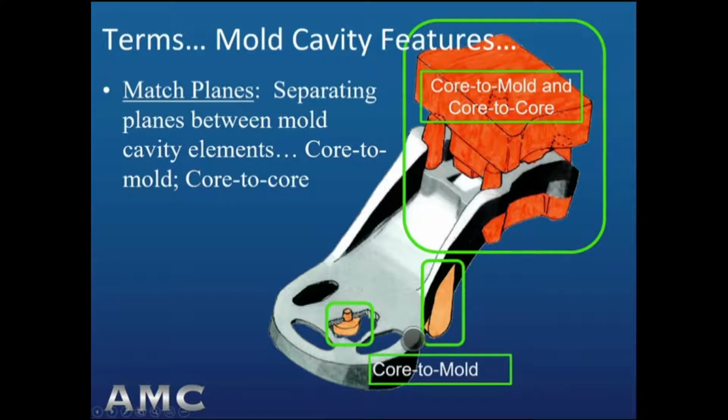At the center right, we see what we call a bootjack core, which forms another hole along the side of the casting, and the bootjack portion of it takes the core up to the parting plane so that the core can be set in the drag, closed over with the cope half, and not leave a portion of empty space for the metal to fill in where we don't want it.